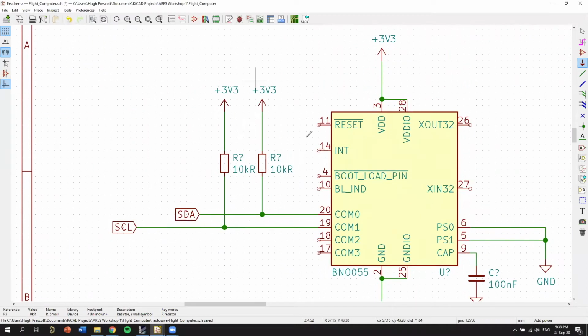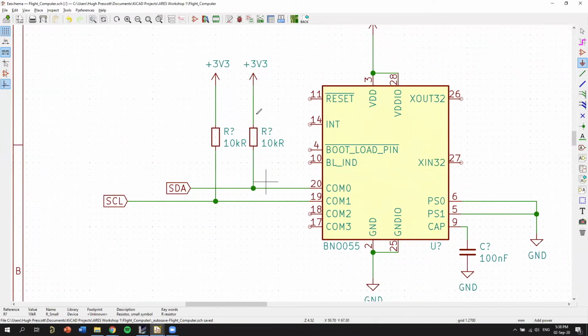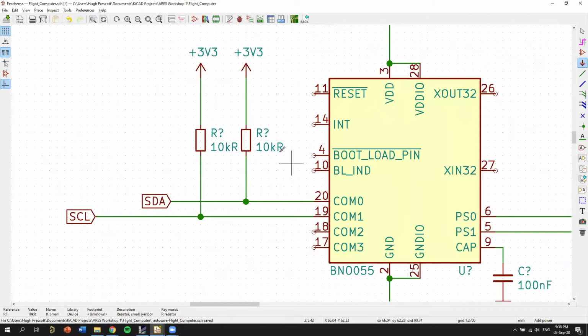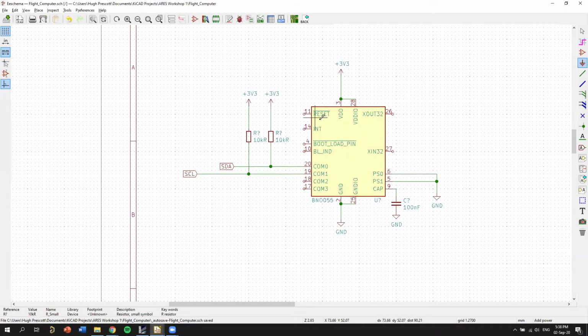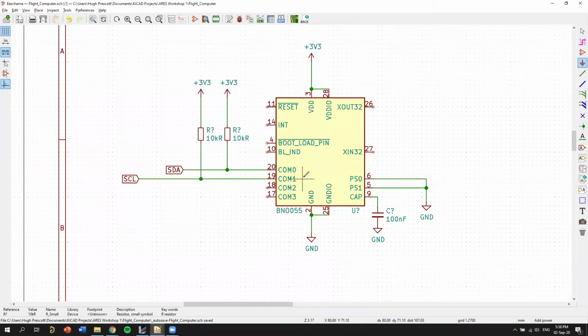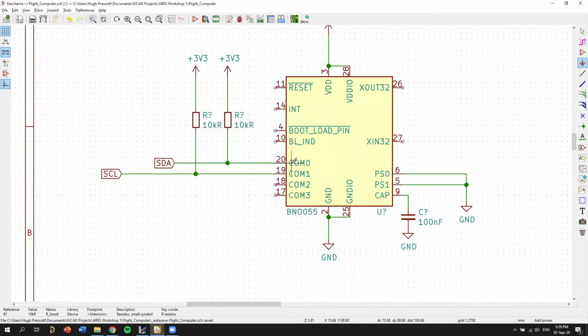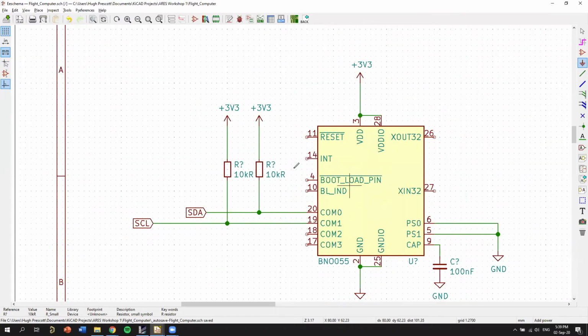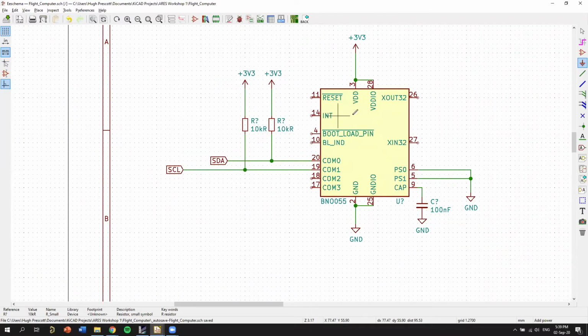It's just for the sake of looking at the range. You can see here, even though you have 3.3 volts here and potentially 0 volts here, that's going across a 10,000 ohm resistor, so you're going to get hardly any current flowing through here. They just need it to work. It's something to do with open drain or open source, something like that. You can look it up. Doesn't really matter right now.